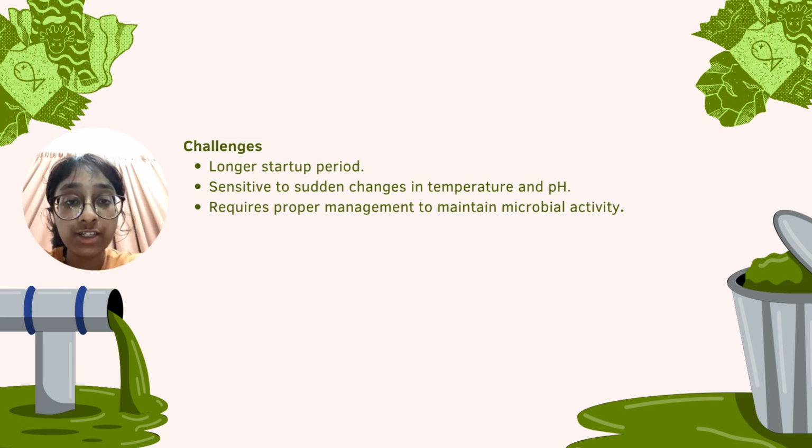However, there are several challenges. Anaerobic systems usually require a longer startup period before reaching stable operation. They are also sensitive to sudden changes in temperature and pH, which can affect microbial activity. Therefore, proper management and monitoring are essential to maintain treatment efficiency.